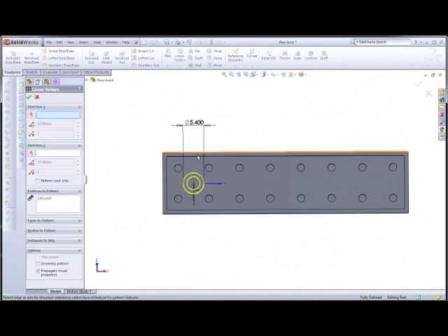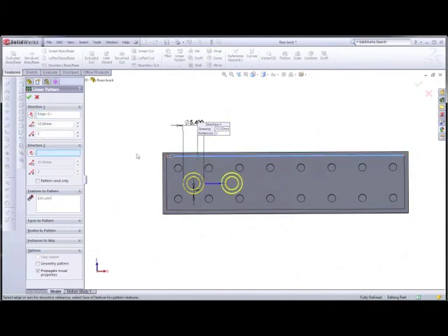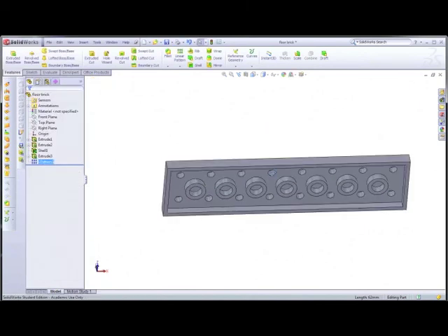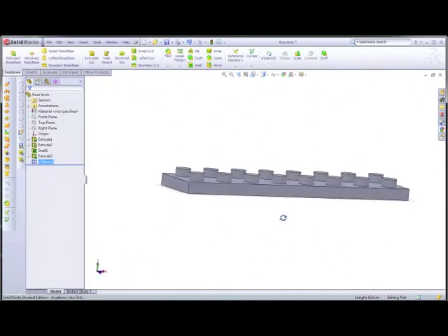Now select the direction along here. Look, and we put 8mm in there. Features to pattern, if that's already selected, it'll appear within there, and then we'll have 1, 2, 3, 4. Okay, so we've got in here features to pattern, that's our feature there, and then we select 8mm in diameter and 7 is the amount, and there we go. Now we've created our floor brick.